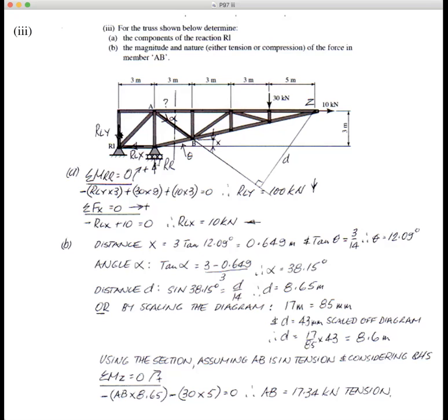So that's why I've put it going down. It just saves you nutting out. If you get a negative, it goes in the other direction. So I've put that force there. Make sure you put it in to show the examiner where those forces go, and make sure you name them, because it makes life easy for the markers and for you when you're working it out.